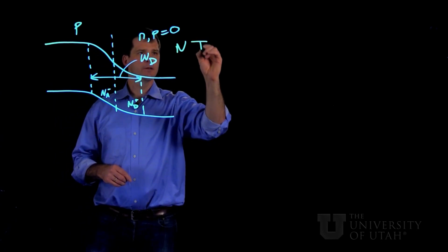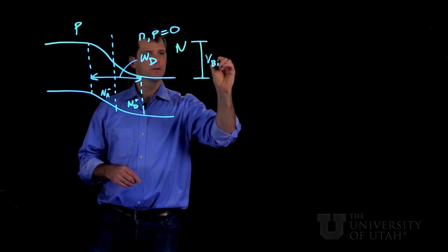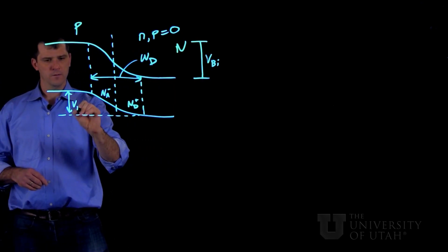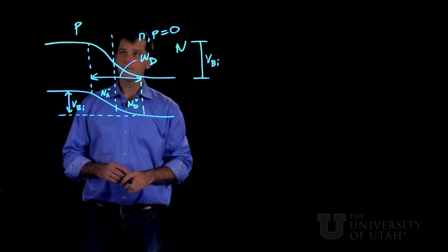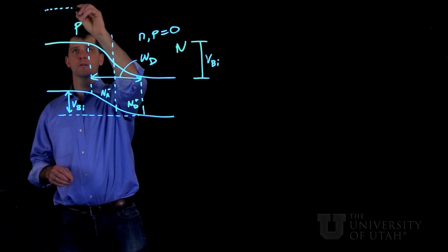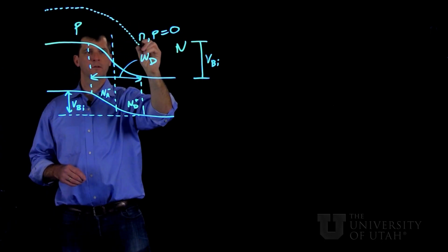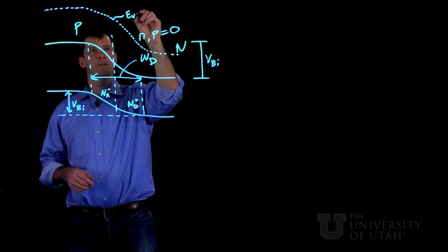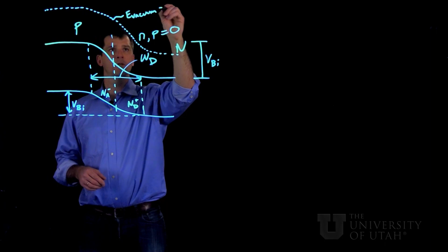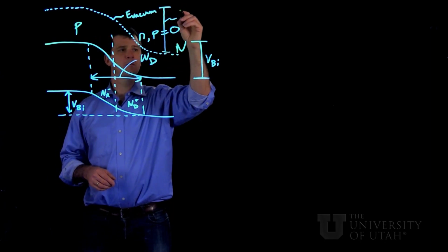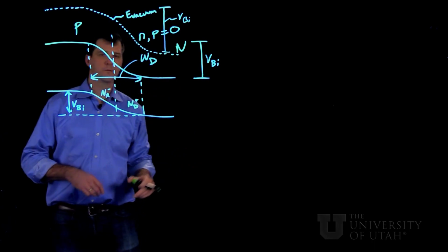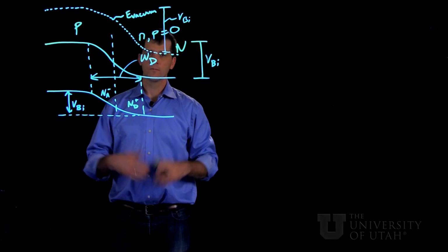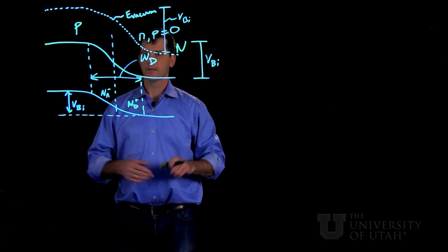Now our built-in voltage, you could measure it from either side. And in fact, I should mention that because it results from an actual charge density in space, the vacuum level also manifests the same amount of built-in voltage too. Just like if you put static electric charges in a vacuum, voltage potential will develop.